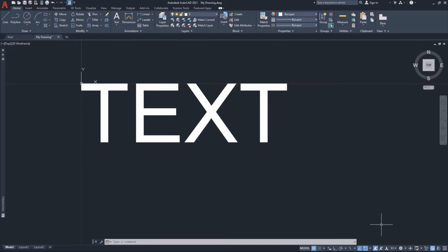The current setting, as noted previously, is 1:1, which means this text object is and will only display in model space at the 1:1 height value assigned to this text when created, which is 3/32 of an inch. The user may assign any number of annotative scales to a singular annotative object.